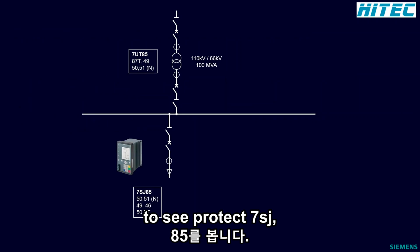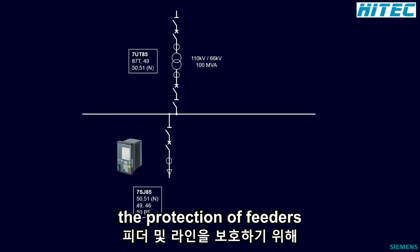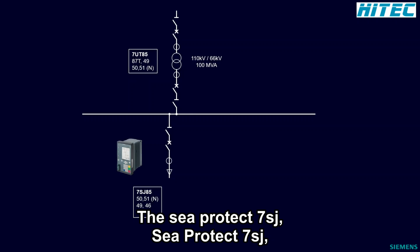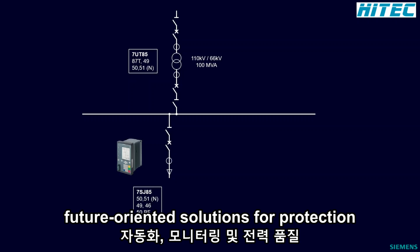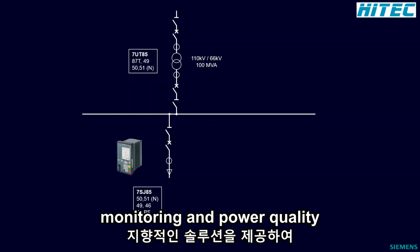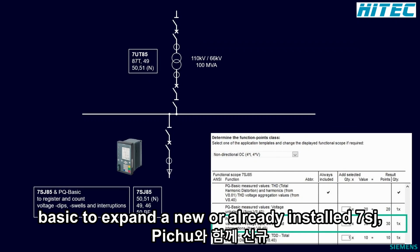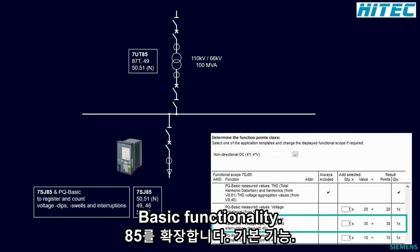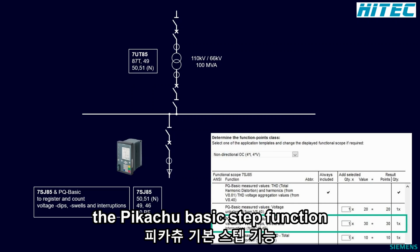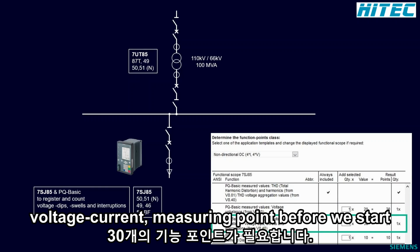In this example, the SIPROTEC 7SJ85 overcurrent protection has been designed specifically for the protection of feeders and lines. With its modular structure, the SIPROTEC 7SJ85 device offers future-oriented solutions for protection, control, automation, monitoring, and power quality. To expand a new or already installed 7SJ85 with PQ Basic functionality, no changes to the installed hardware are necessary. In our example, the PQ Basic subfunction voltage variation requires 30 function points per voltage current measuring point.